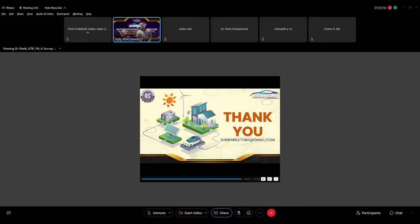And how about the charging? Because now, as I know, the charging time is quite long. Charging time is high, yes. Charging takes 6 to 8 hours for a level 2 charging station. But there are more rapid charging stations coming into the market. The recent one charges the vehicle in 20 minutes, and I heard that there is a 320 kilowatt DC fast charger which will charge your car in 10 minutes. Technologies are coming, but it will take a bit more time.